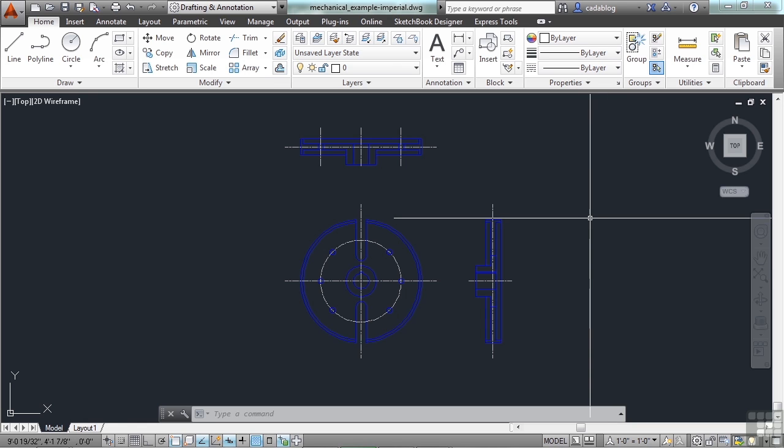When you draw, make sure to know what units you are using. Your units can be anything. In fact, they can be feet, inches, meters, kilometers, or even parsecs. It doesn't matter. What does matter is that you draw to full scale or real scale, and you only draw in one unit. There is a units setting in AutoCAD where you can declare what your drawing units will be.